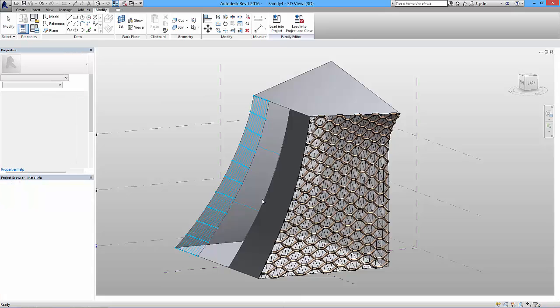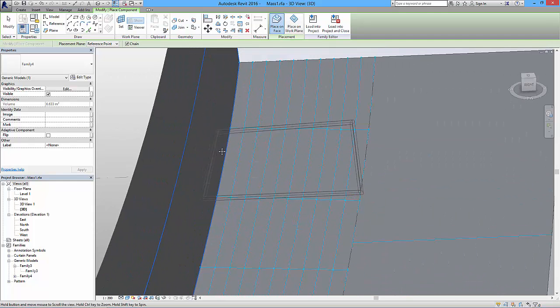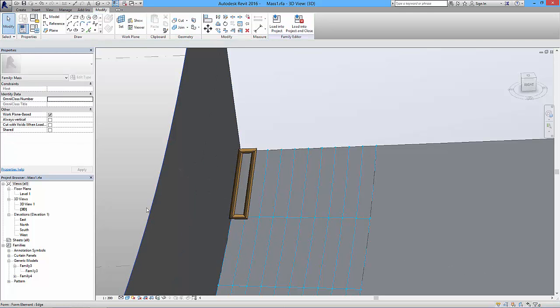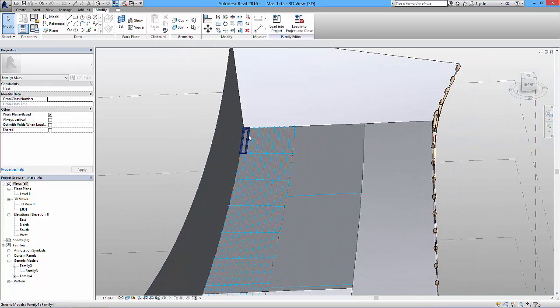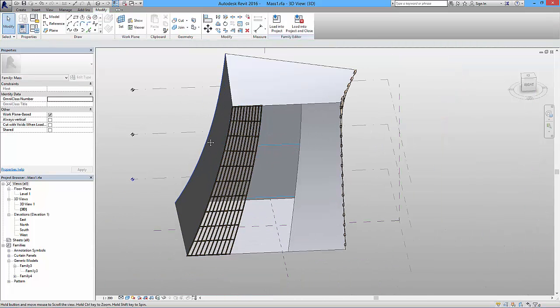So I say OK to that, and then here it is, attached to the end of my cursor. So then I'll come up to these node points, and it's important that these are turned on, otherwise you couldn't snap to them. And I'll click there, and then it's adapting to the shape. So 3 and 4, and then hit escape. So that's what I've created. Now I can select this form, and then I get this option on the modify. It's like an array, but it's got a little P sign next to it. It's the repeat. So if I click on that, then it's going to just repeat this pattern on this grid. It's a very, very nice function.